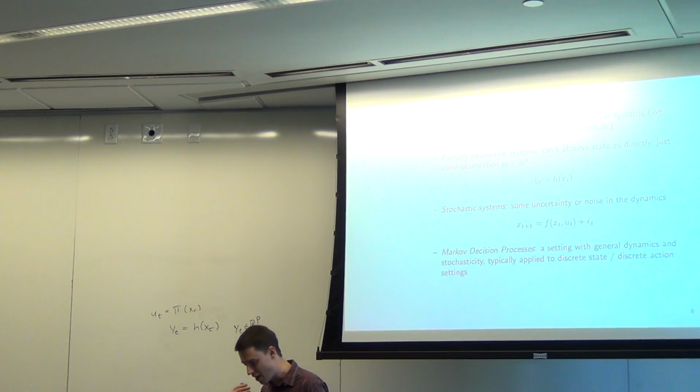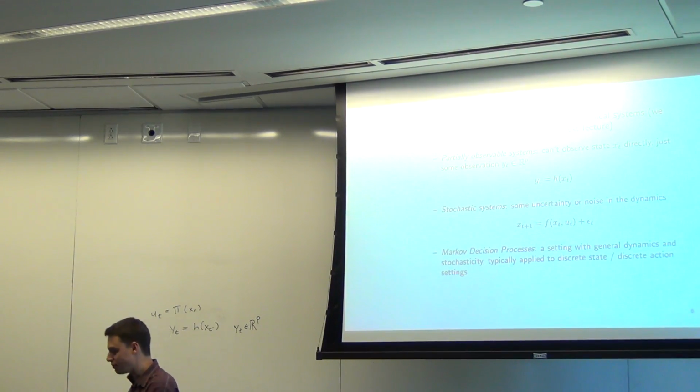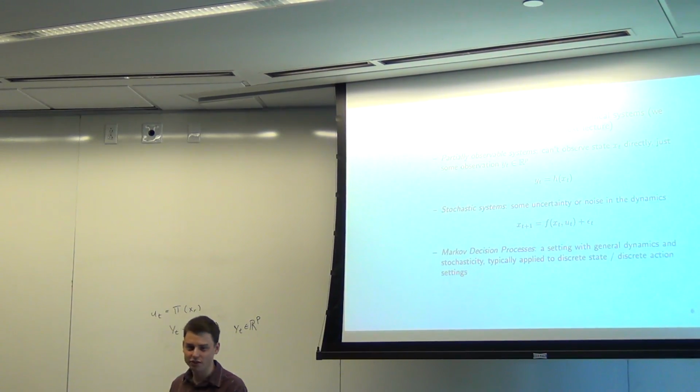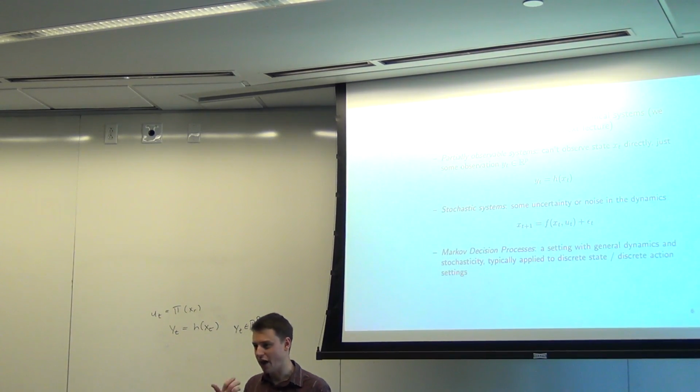This is an aside, but for a long time it was very hard to figure out what voltage angles were, because what matters is the relative voltage angles at different points. So how do you compute that very quickly? It's being done now through GPS clocks, essentially. You get some fixed time reference and you figure out where you lie relative to that. But before you had that, it would be very hard to know what your absolute voltage angle was.